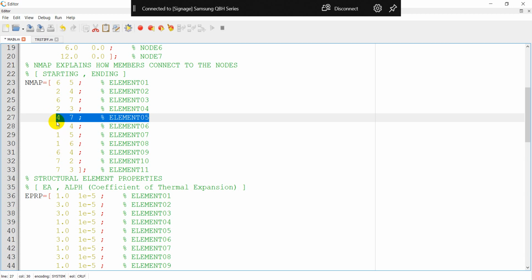For the 4, 7, the node number 7, DOF number 7, 8 will be at the first 2 rows and columns. And for the number 7, it's going to be 13 and 14. So you can imagine that things in the 4 by 4 matrix have to go to the right place in the cases that will be programmed.